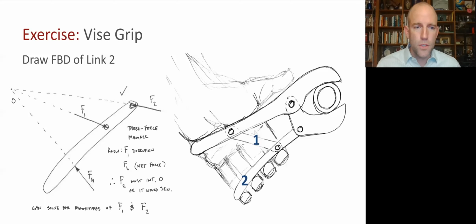So this is a case of what's known as a three-force member. Where in a two-force member, both forces are collinear and equal and opposite, in a three-force member, all three forces point at the same location. They all intersect at the same point. And if you had something different, a quick check that could help identify an issue would be to ask: is static equilibrium possible with the forces and moments that we've put on the page?